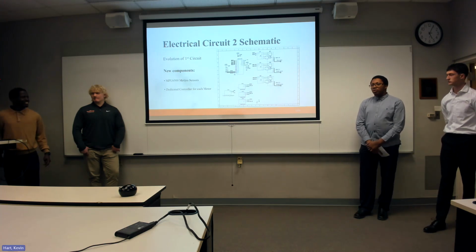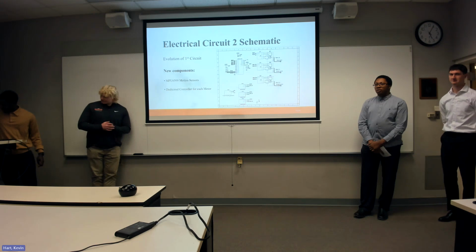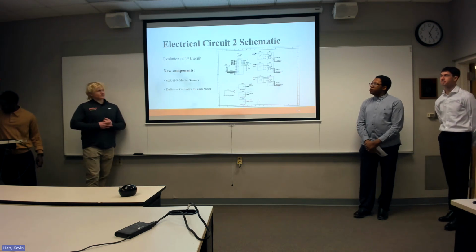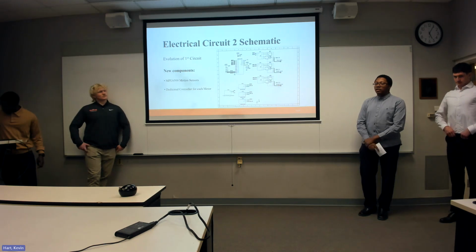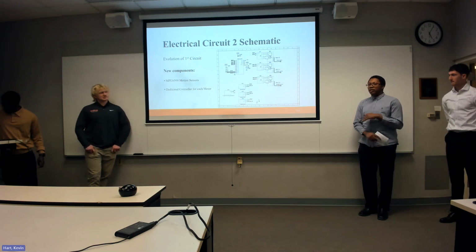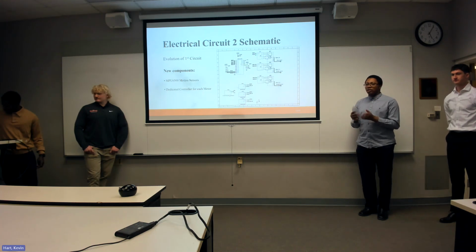Do you use PID control or other algorithms you have in mind based on your literature review? The motor specifically just needs a step and direction, so based on the angle, it'll define the step, and then depending on what phase of the walking cycle we're in will be the direction.